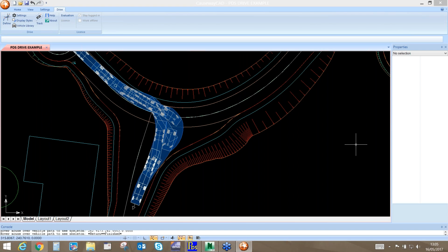A question from Stuart in Flow. Is there a conduit designer? Yes, there is. Because of the time constraints, you can generate different conduits and build that up as a library. So you can build in swales and have those swales follow the ground levels. Or if you want to put in culverts or splayed edges, you can do all that and set those yourself. Thanks, Tom.